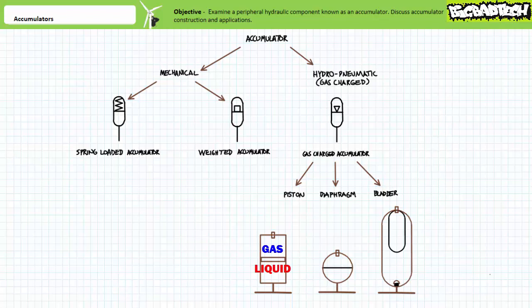A piston accumulator consists of a cylinder sealed by a gas cap with a charging valve on the gas end and a hydraulic cap at the hydraulic end. A lightweight piston separates the gas side of the accumulator from the hydraulic side. A diaphragm accumulator swaps out the piston barrier with a flexible synthetic rubber disc between the top and bottom halves of a spherical vessel. As pressure changes, the disc distends and supplies or absorbs pressurized flow.